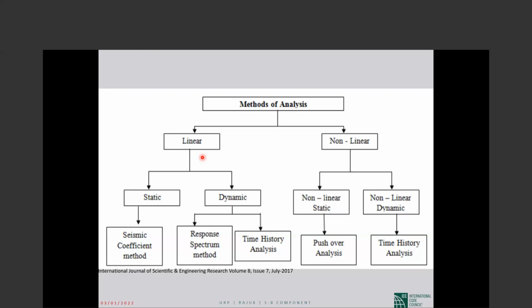So the general approach is not that difficult. Now, when we want to calculate the capacity for the force control actions, there is nothing new in the code for existing buildings. All the formulas for capacity calculation are the same. Just the value of f prime c or fy that we want to put in the formulas will be lower, the average minus 1 standard deviation.